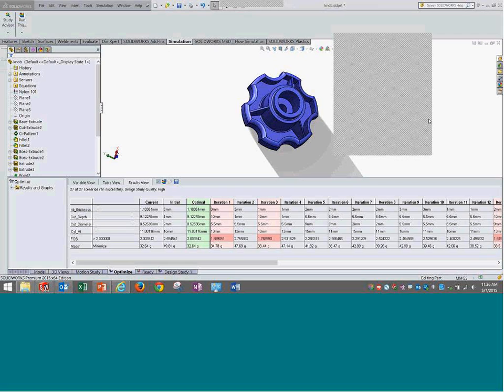Can it be used to simulate the stresses and deflection in sandwich composite panels? So yes, it can simulate composites. We do have a module for composites as well, but it simulates only layered composites. However, it depends on the thickness of the composite. If it is simulated as solid elements, you can have multiple solid layers and do it, or it would be multiple shell elements. Both can help you simulate composites.